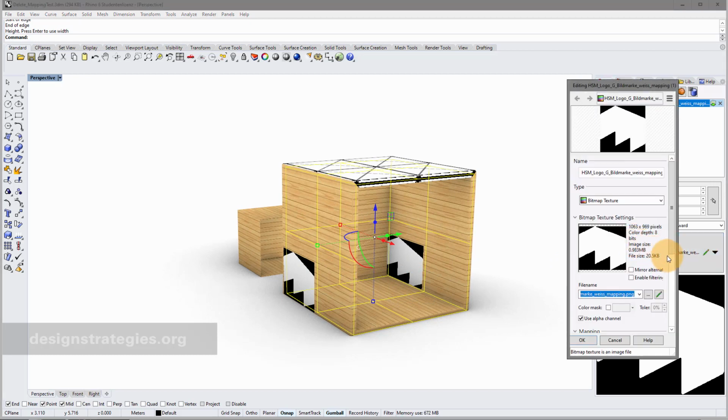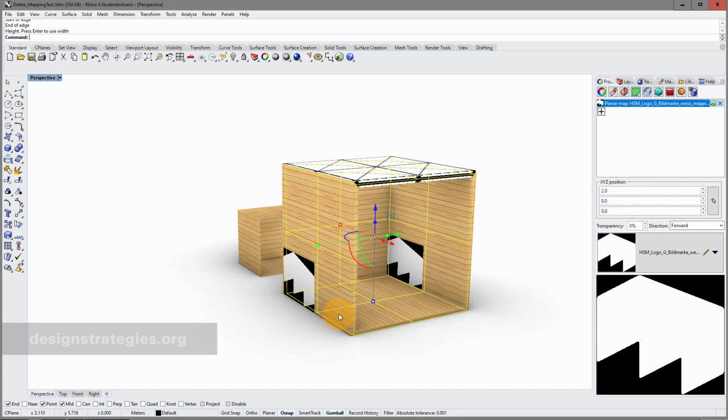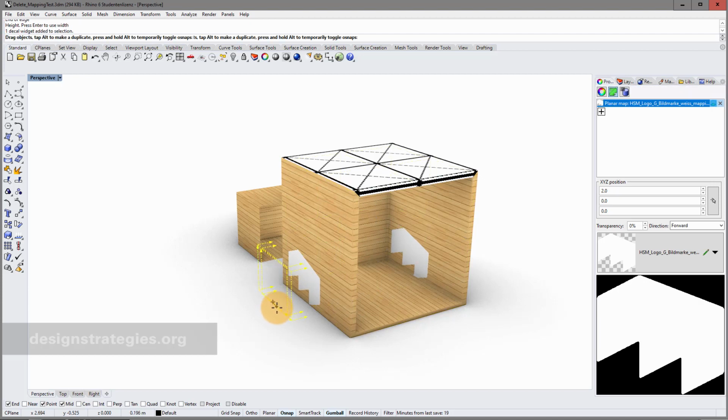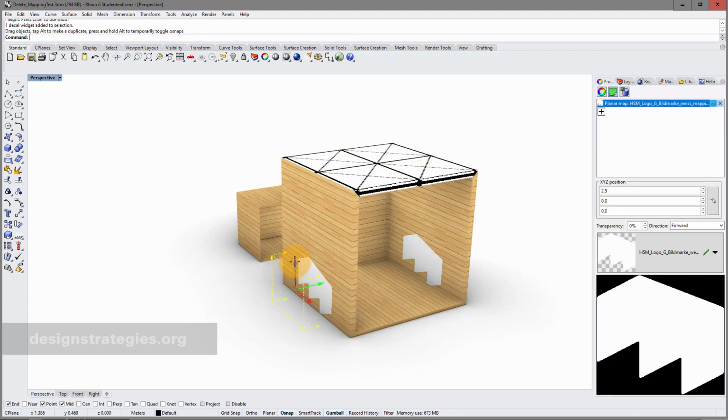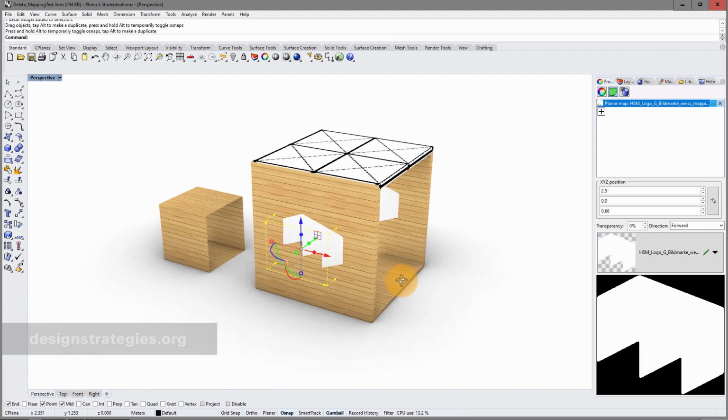I go into the settings, and if I use a color mask and click OK, then you can see that it is actually transparent. You can move the decal. Furthermore, you just click on this Show Decal widget. And now I can grab this and move it up. I can move it in all directions wherever I want to have this.